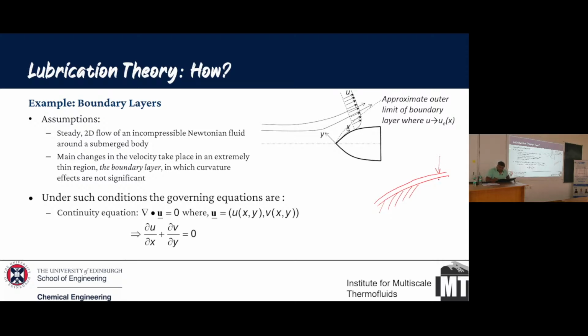And typically the boundary layer thickness is given by delta naught. Okay, it's an approximate. So this is how your boundary layer is in comparison to that. So one thing we quickly say is delta 0 by L, if L is the length scale of the wall, is much smaller than 1. Okay, much smaller than 1. So obviously if you consider this region, it's almost looking 2D. Yeah, boundary layers also have 3D features, but if you look at it from that perspective, they are essentially 2D.